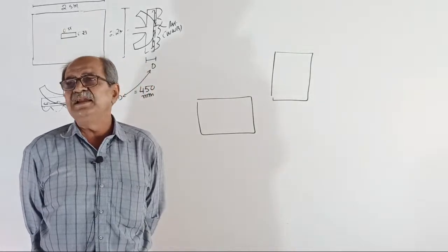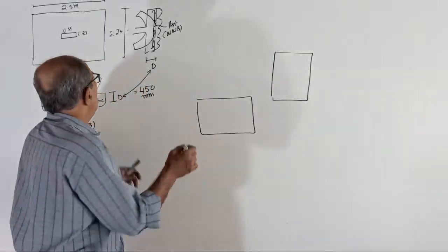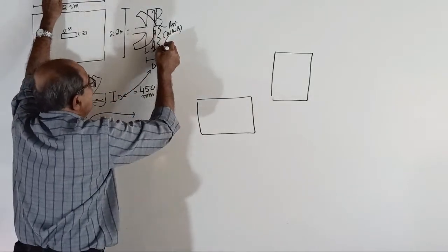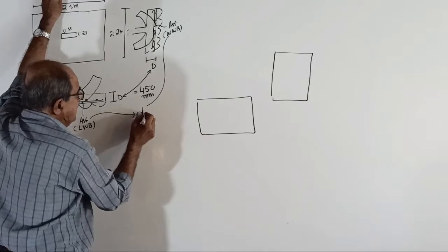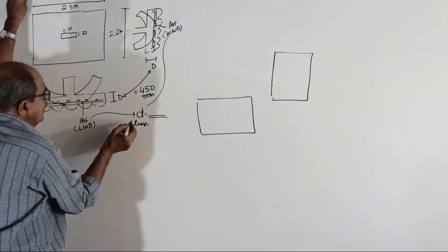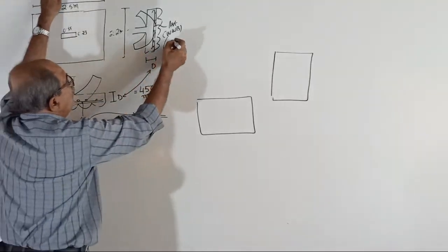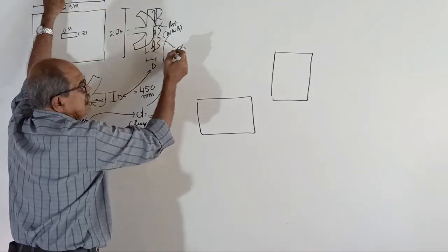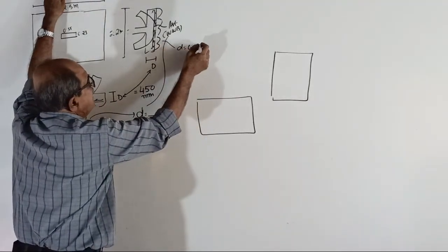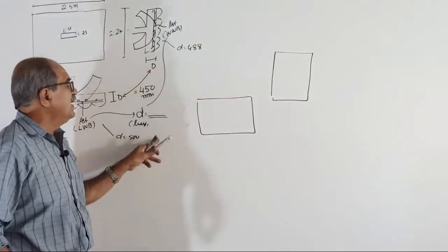See, you are unnecessarily taking more D. So to safeguard that one, practical design, what will you do? For both lengthwise bending steel and widthwise bending steel, we will take the least value of D. Why? For example, lengthwise bending D is 500, randomly. Widthwise bending steel D, suppose you are using a 12 mm diameter bar, it will become 488. Okay, then compared to that the difference is 12 mm.